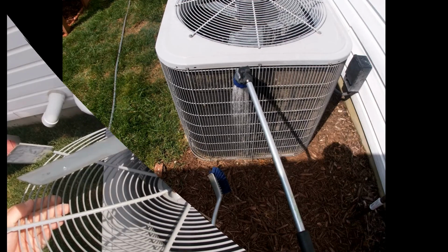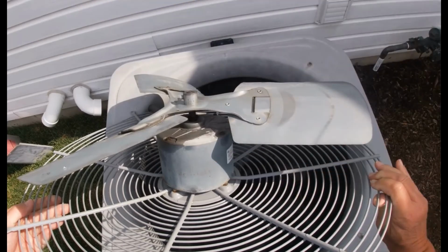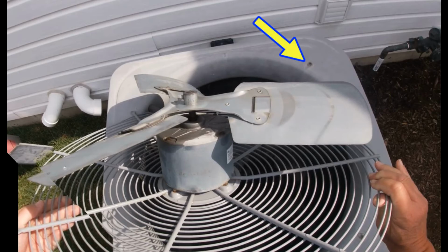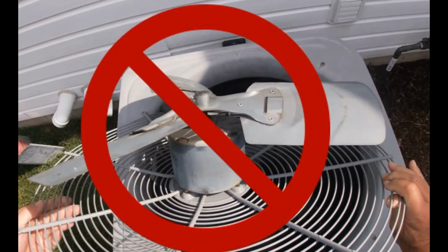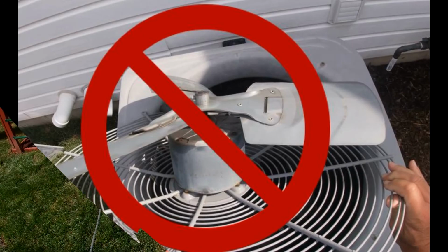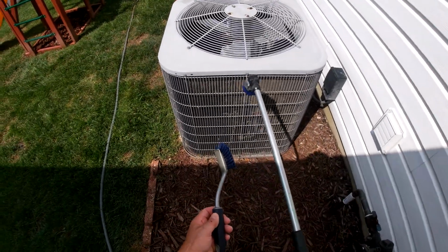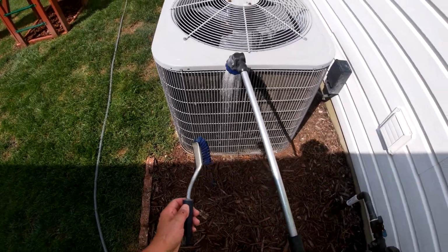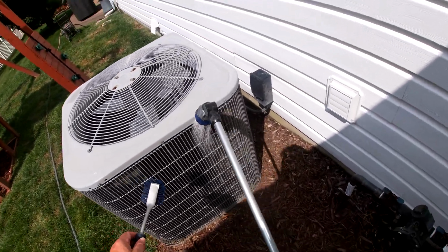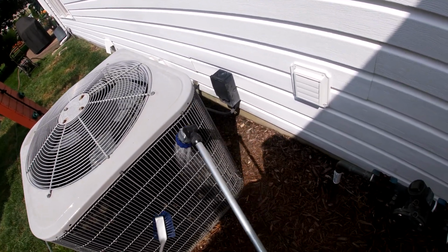You can clean it best by removing the fan shroud on top of the condenser, but frequent removing and installing these mounting bolts will damage their sheet metal holes and cause you major problems with this structure coming loose. Consequently, I strongly recommend against that also. Using your garden hose, I recommend that you clean the condenser by starting at the top of the coil and spraying and cleaning with a downward motion until all of the dirt and debris are gone.